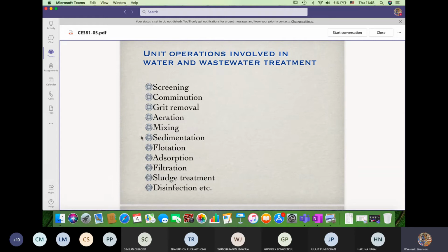As they are very light, we make them lighter. So we provide air bubbles. We supply the air bubbles at the bottom of the chamber. We actually create very fine bubbles. The bubble size is just 0.1 or 0.2 millimeters. Once these fine bubbles blow out from the air blower, they get attached to the particles and make the overall density lighter.